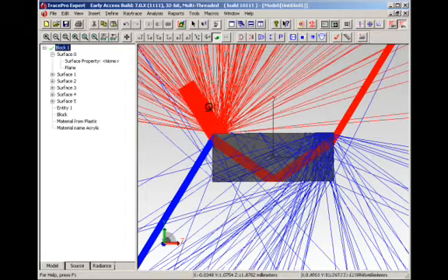So exactly what we expect to happen is that half of the rays strike the surface, go through, and then are TIR'd at this particular surface, and then come through as we would expect. What are the blue rays? The blue rays are the Fresnel reflection on this particular material. On the top we painted it with white. There's no Fresnel reflection there. So therefore, all we're going to do is get these rays to scatter off from that particular surface as a white diffuse paint would do.